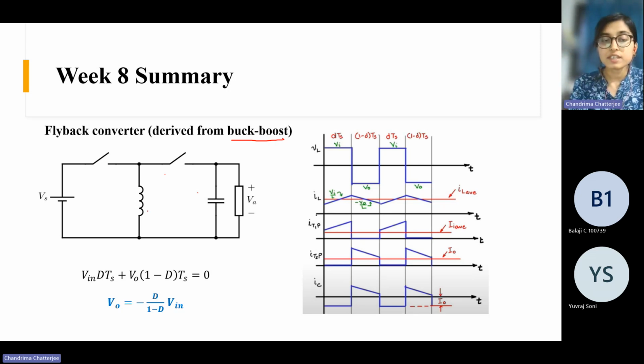So now the inductor is connected like this. Here will be one semiconductor device. When the semiconductor device will be on, the inductor will get energized in this path. And then here we use a diode for the buck boost converter.